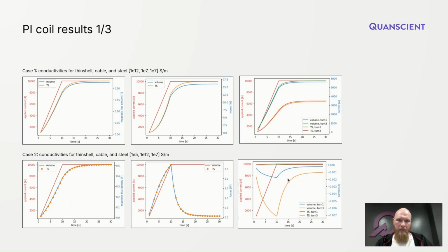However, you can see differences now in the net currents. However, if you compare the amplitude of the current, it's negligible to the applied current. So this is basically a noise level signal in the Thinshell, and this can be really affected as well by the mesh. So the mesh is not that accurate in the Thinshell model anymore, since we are using bigger elements there.